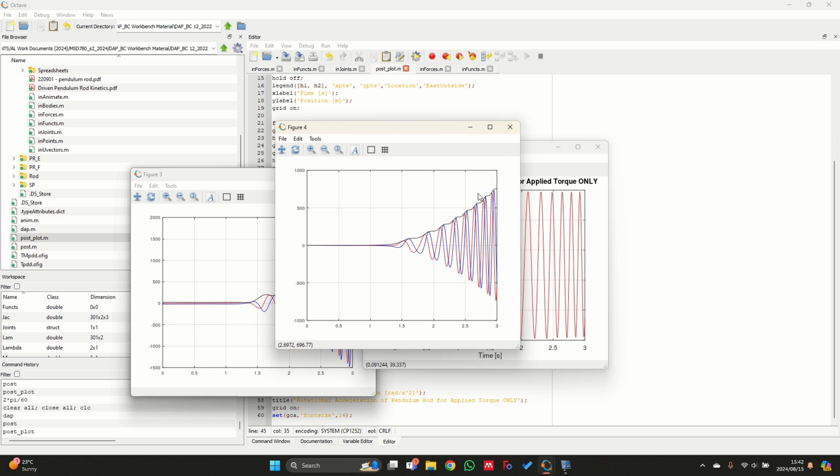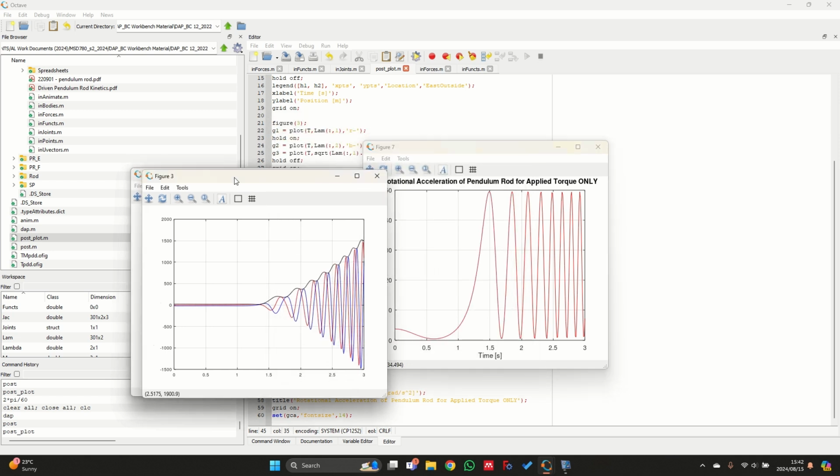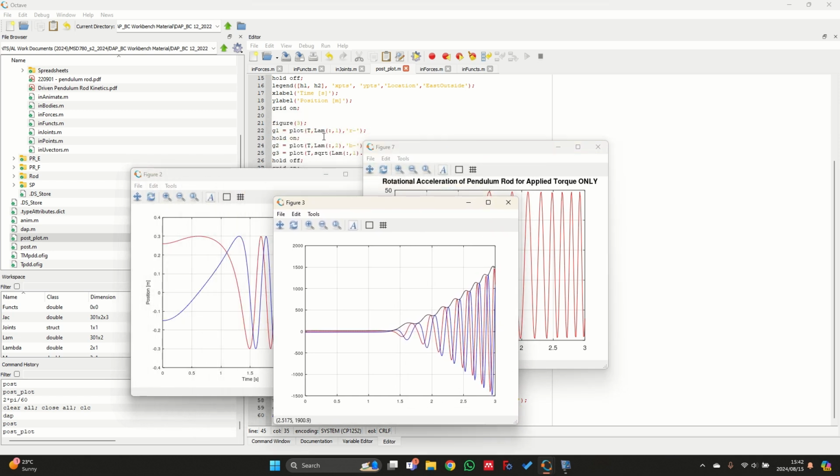So there is no braking torque being applied over here since we don't have any acceleration limit specified. Then you can also check figure 3, which is just the reaction forces. Once again, these reaction forces are much larger. Previously, with the braking torque, or the relative rotation driver specified, the force was around 20 Newton. In this case, our force after 3 seconds is already at 1,520 Newton.